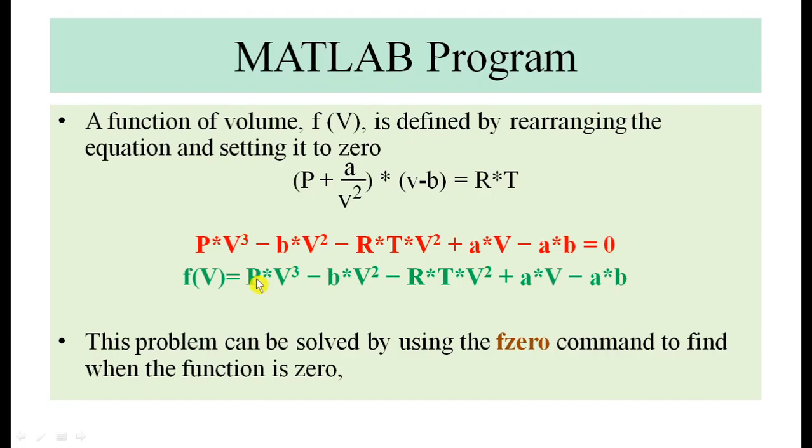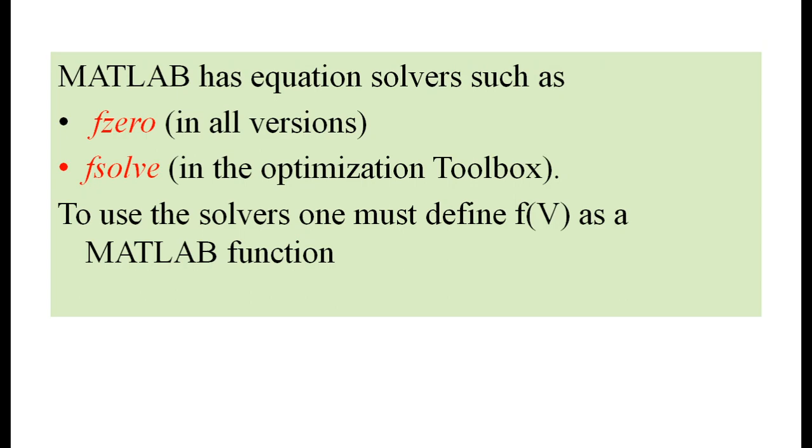This f(V) is what we are going to solve, that means we calculate the root of the equation to get the volume. For calculating the root of an equation, MATLAB has different solvers. One of them is fzero and another is fsolve. To use these solvers, we need this function f(V).